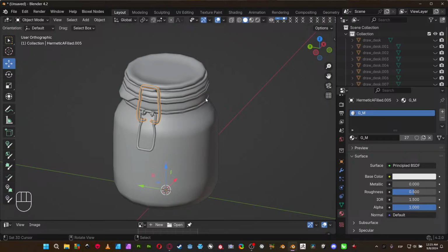The third one is, if you want to make small changes and you don't want to go back to Mari or Substance Painter, you can use Photoshop, Affinity Photo, or an image editor to change things or clone things directly on the map, the PBR or things like that. But if you don't have UVs, you will not be able to do that. The fourth thing is very important. This is something very technical, but I want to share it with you because many people don't take care or don't care about it.